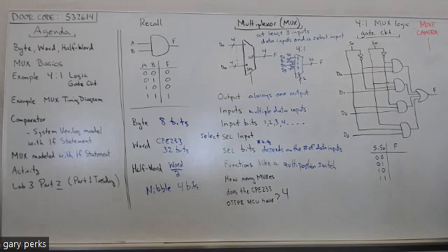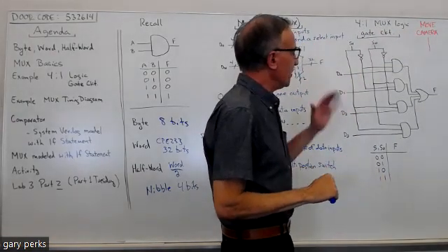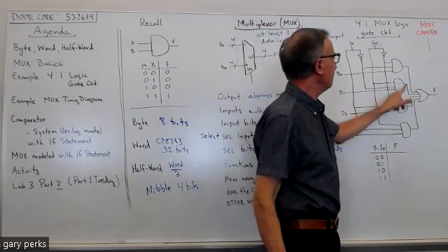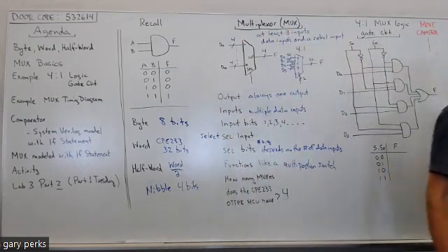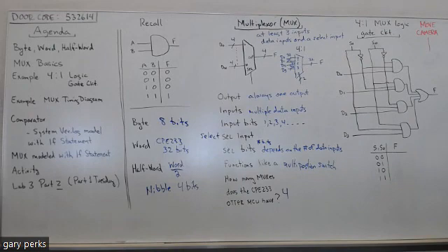All right, so the next thing, unless there's questions, is to look at the logic gate diagram of a mux. And this is an example of a 4 to 1. This 4 to 1 mux, the way it's made with gates, you've got 4 AND gates, an OR gate, and a couple of inverters. So here's a pop review question. What kind of logic circuit format is this? Is this NAND, NOR, SOP, POS?